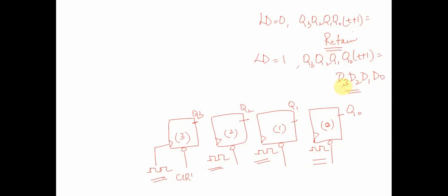Have we seen a combinational circuit like this before? Remember, we looked at this nomenclature and we called this circuit a multiplexer circuit. Basically, depending upon the select line, one of these 2 raised to the power n inputs will be connected to the output. So if we draw a mux circuit, a multiplexer, the output would be either Q3 or D3 depending upon the load, correct?